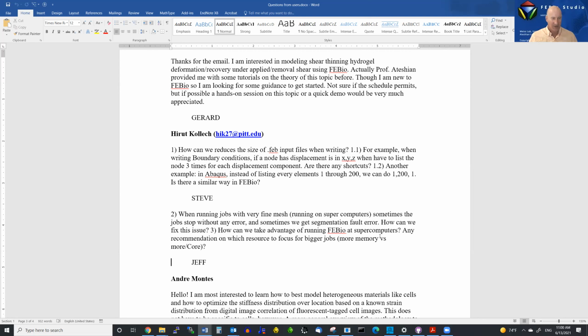Okay, anything else here? Or are you good now? Yes, but just to clarify my earlier question about the mesh convergence, which I put in the chat earlier. I was trying to create a mesh convergence plot while varying the mesh size. Right now, the way I'm doing that is by outputting specific nodes around a specific XYZ location in space, and I do that in every job.